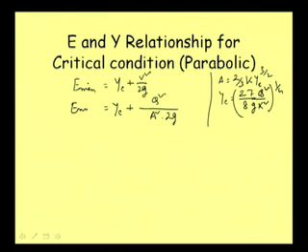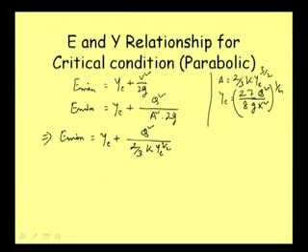Starting from that, what we can write, this implies E minimum is equal to yc, and let me again rewrite this expression, yc plus q square, let it remain like that, and then area we will be writing as 2 by 3 k yc to the power 3 by 2 this square and twice g.